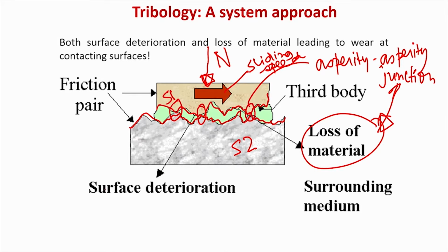So, what it means is that a material, based on whatever surface finish or polishing, may appear to you as extremely flat, but in reality it is not extremely flat. In much of the literature, it is mentioned that the material is nominally flat, but nominally flat materials also have a finite number of asperities, and these asperities have a certain radius of curvature and surface height.